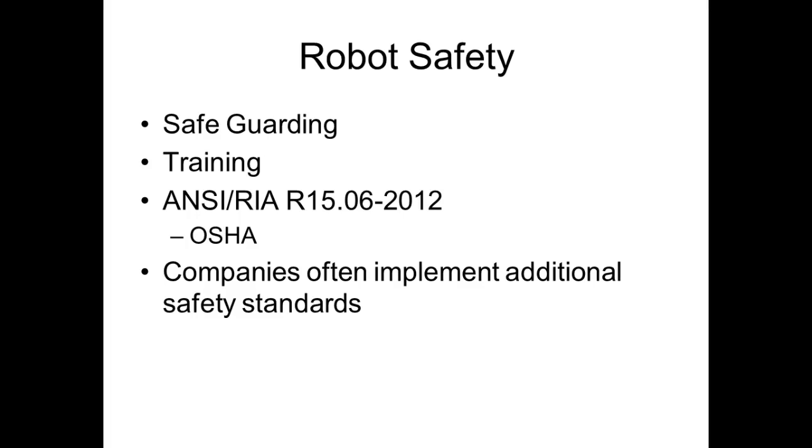They think the circuit breaker is there to protect the load. Circuit breakers are not designed to protect the load. They're designed to protect the conductors that provide the load, the wires running through the walls in your house. Otherwise the house is on fire. So if you've got a 15 amp circuit breaker that's popping, don't go out and buy a 20 amp breaker to put in there, even though that sounds like something my father-in-law would have done.